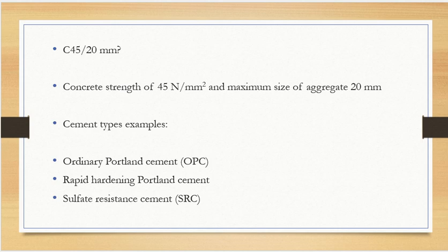And then you can change the type of cement within the concrete, and these are the main cements we have. Which one is more applicable for hot climate? Second one. Why? Because it is rapid hardening. If you leave the cement paste or concrete paste for too long, water will evaporate. So we use rapid hardening, so the reaction is finished fast. Concrete hardens, with less evaporation of water.